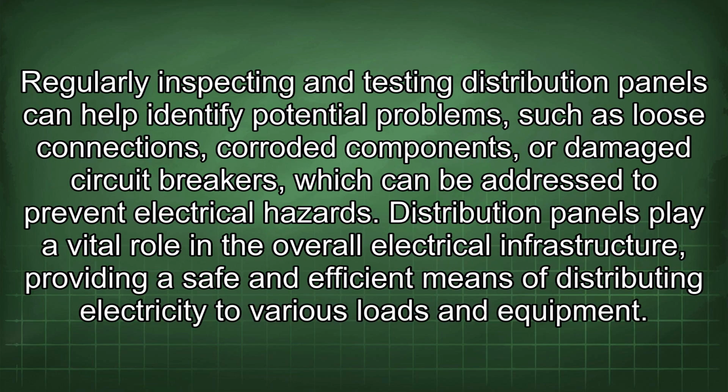Regularly inspecting and testing distribution panels can help identify potential problems such as loose connections, corroded components, or damaged circuit breakers, which can be addressed to prevent electrical hazards. Distribution panels play a vital role in the overall electrical infrastructure, providing a safe and efficient means of distributing electricity to various loads and equipment.